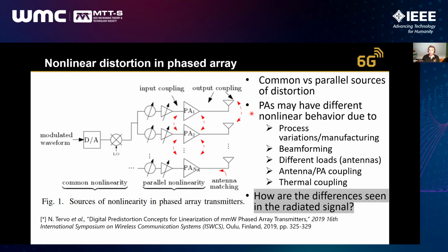And even if you wouldn't control the amplitude, you still have a phase shifter that has a gain. That gain may vary a little bit as a function of the phase shifter code word, for example, and that has some impact on the signal amplitude, and there are small errors there that actually weight the power amplifiers. So this makes the distortion at the amplifier outputs have some differences.